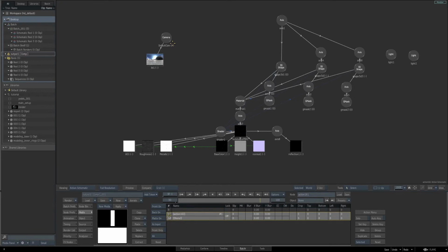Hit the M key to go back to your select tool. Make sure the image, the media that we just brought in, is selected in your media list. And then also make sure you have selected the IBL source attached to the camera. Then come down to the parameters and click the Apply button.